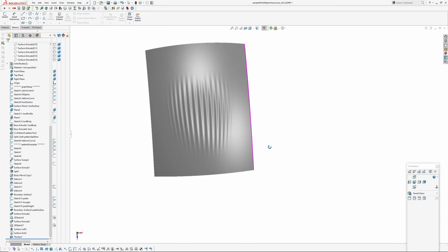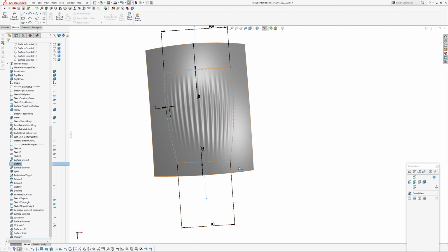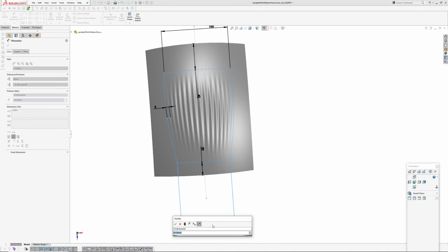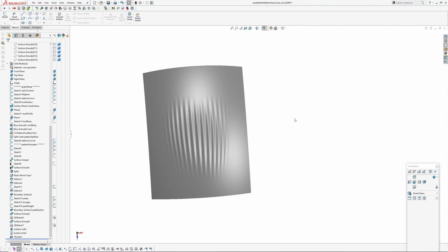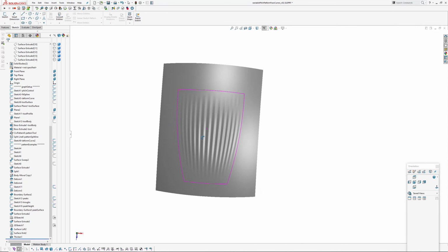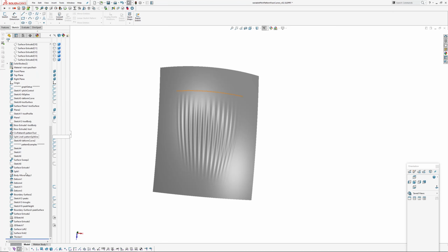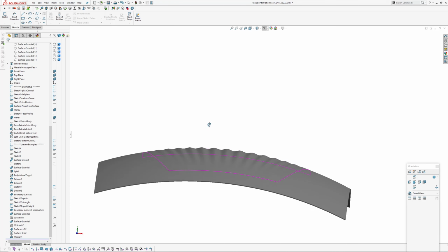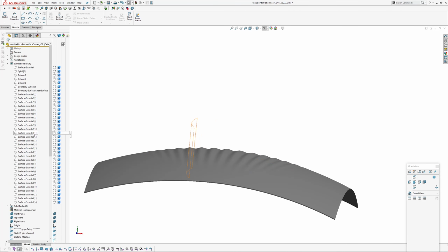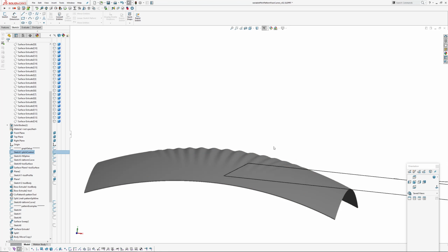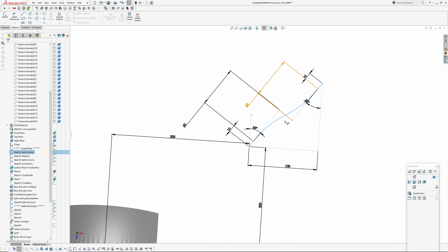And again, this is fairly flexible, so if we want to change the shape of the split or the boundary of the pattern, I just have to go down here to the extrude that cuts it out and rebuild, and that updates. And what else can we do? The pitch of the pattern. Okay, the pitch control here.